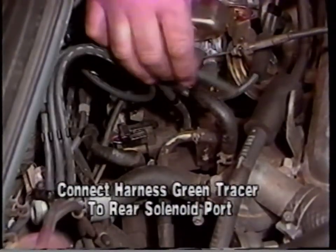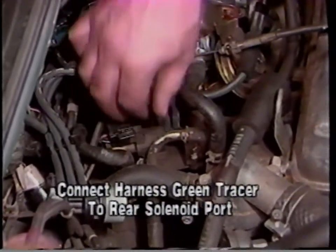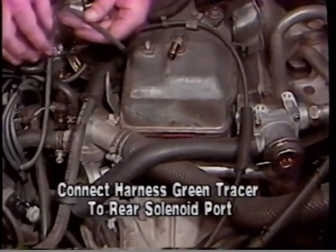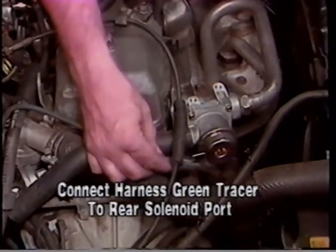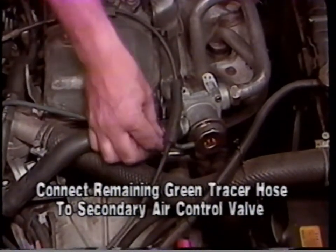Connect the green tracer hose from the harness to the rear solenoid port. And connect the remaining green tracer hose of the harness to the secondary air control valve.